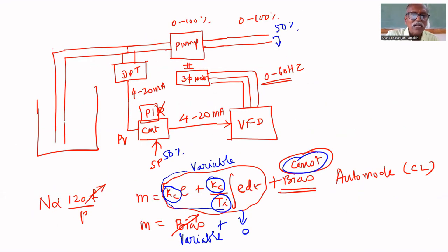For that, we have to put the controller in closed loop initially. Give some set point. Give minimum gain, because it is not K max. Give minimum gain. It means give maximum PB.